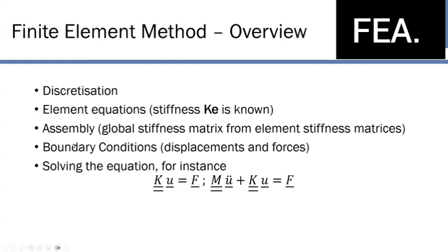We're going to apply boundary conditions. This will include applying any conditions that reflect reality, be it supports, be it loads, etc. And then we solve this whole thing using linear algebra to solve an equation such as the ones we have here, Ku = F, or M u double dot + Ku = F. So it's very rooted in stuff that a lot of you have probably done: MAE 101, statics, MAE 156A. I've probably TA'd. I recognize a few of your names. So some of you should have that background, at least with regards to me, on how to approach these problems.